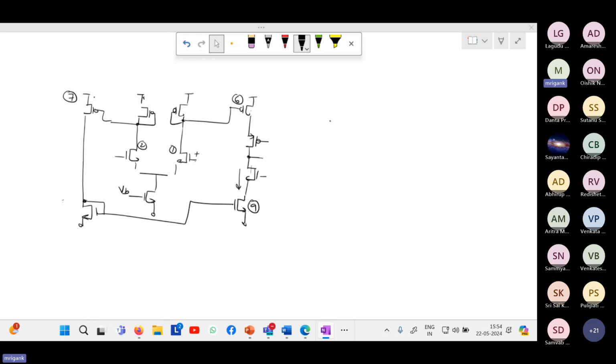So yesterday we had seen that if you use resistive feedback, it can have some loading effect on the output resistance, the overall output impedance. That is a good point. Because if you look at the feedback resistance, if you are using feedback between the output and the negative input like this, and for the resistive feedback scenario you consider the loading effect, you will need to basically break this R. So you know how to basically get the loading effect for the feedback.